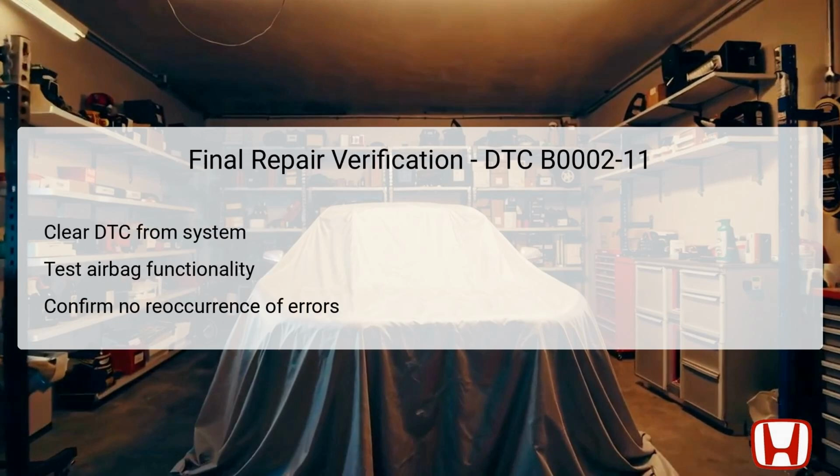After completing the necessary repairs or replacements for any faulty components related to DTC B0002-11, it is vital to conduct a final repair verification. This involves clearing the DTC from the system using an appropriate diagnostic tool. Once the code has been cleared, the next step is to test the functionality of the airbag system to confirm that it operates correctly during a deployment sequence.